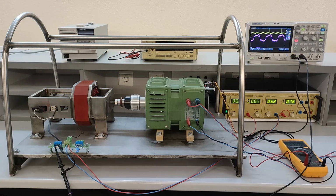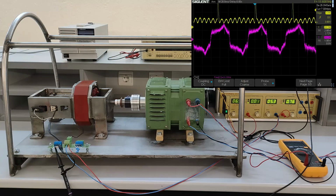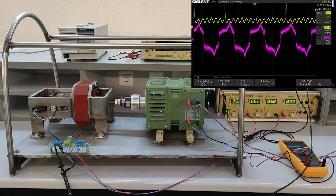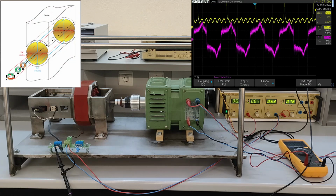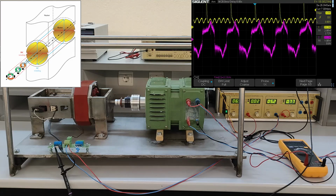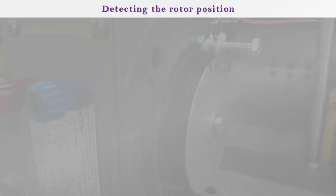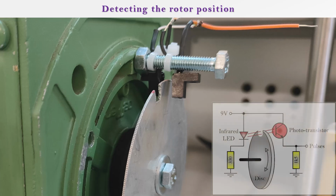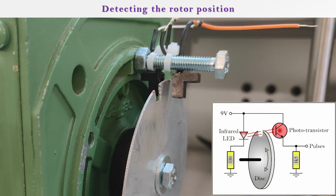The oscilloscope displays the induced voltage in the armature winding, and also a pulse that defines the position of the rotor. When the pulse is high, the AC armature winding is in the middle of the stator poles. The pulses are obtained by fitting a disc with a notch on the rotor shaft and using the electronic circuit shown.